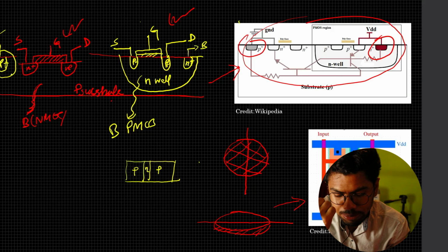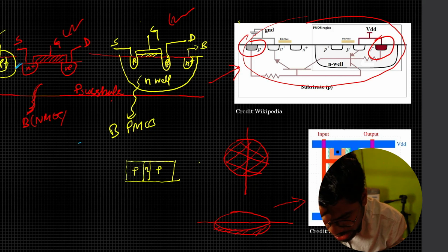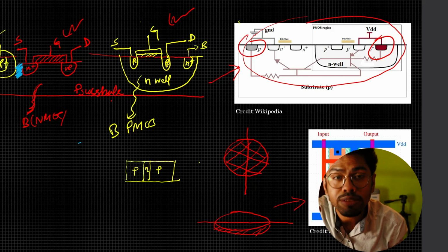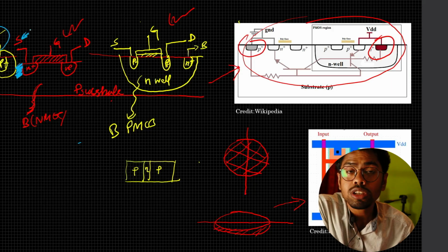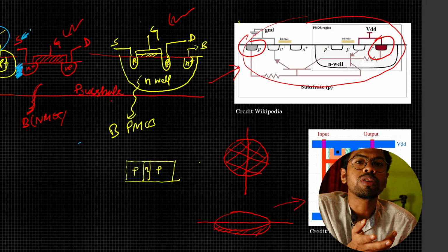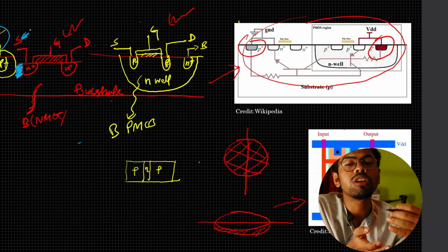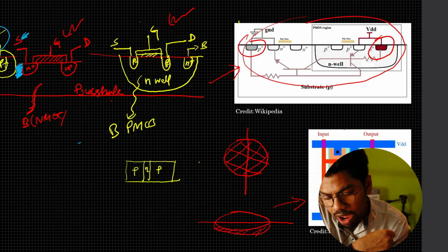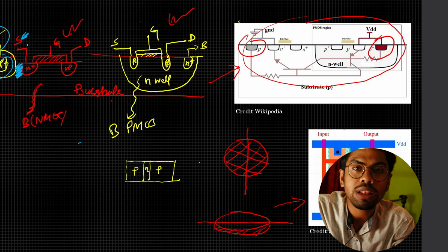We want that our MOSFET should never get forward biased in this junction. For example, here we have one junction, N and in between P, because the source could be tied to some other potential, we don't know, right? It could be 0 or it could be something else. But if our P gets more potential than the source, then the problem will happen.